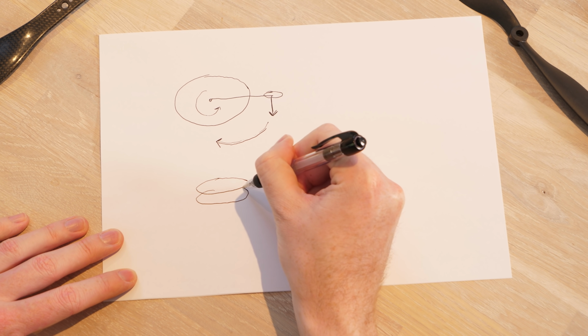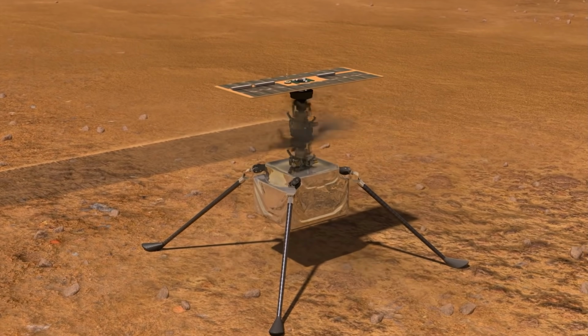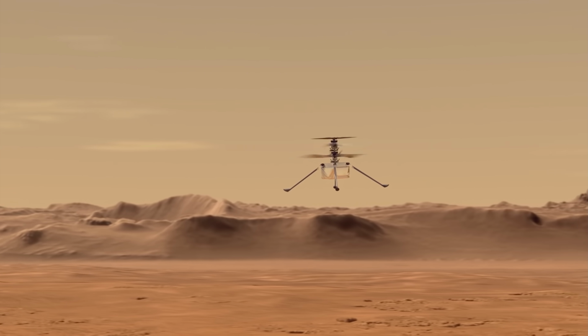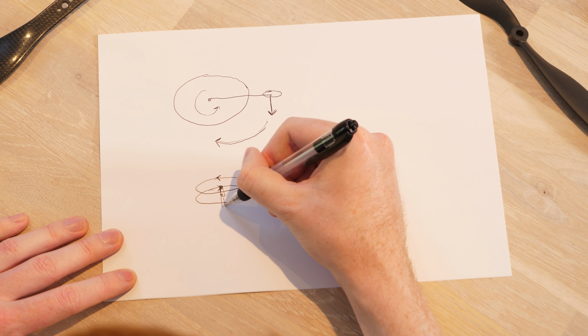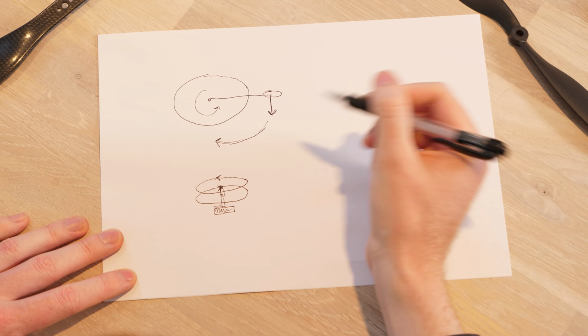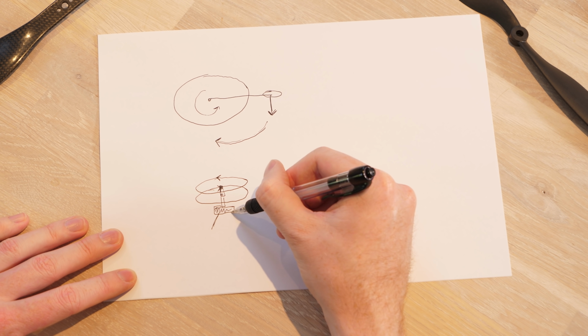But what about a helicopter with contra-rotating blades like the new Mars helicopter, where both blades spin in opposite directions? This would counteract any rotor torque, but would also mean we need to build a gearbox and shaft system so that each propeller could spin in opposite directions, which isn't a problem for an electric aircraft, but because these air turbines can't produce much thrust, it's probably going to produce too much friction with the gearbox and also a lot of weight.